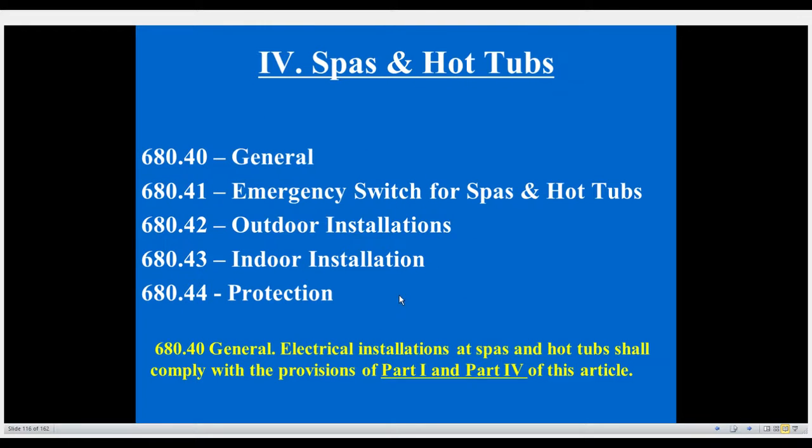Now you're going to see that when you get into outdoor and indoor installations of these spas and hot tubs, it's also going to require you to meet the requirements of Part 2. And of course, it's going to change some of the requirements, for example, the equipotential bonding. If you meet certain requirements, it's going to say you don't have to do that if you meet these requirements. And if you don't meet these requirements, guess what? I did tell you, you've got to meet Part 2, so then you're going to have to meet the equipotential bonding requirements.